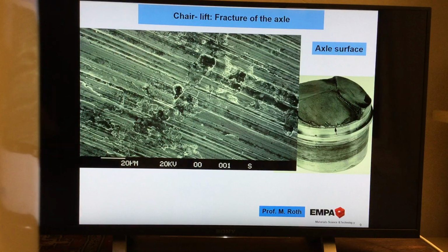There's different possibilities. There's also a possibility, which was argued, that there is something stuck, another material here on the surface. How can we investigate this? Very easily. We can make here, when we are anyway in the scanning electron microscope, X-ray analysis in the microscope, and I can tell you, we only could find the elements of the steel, nothing else.